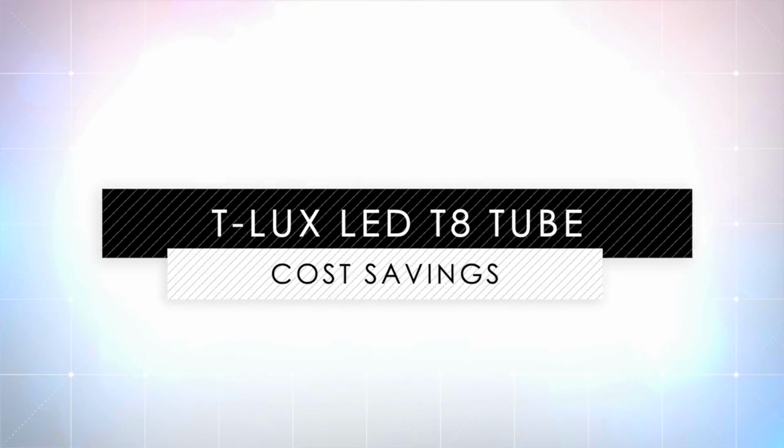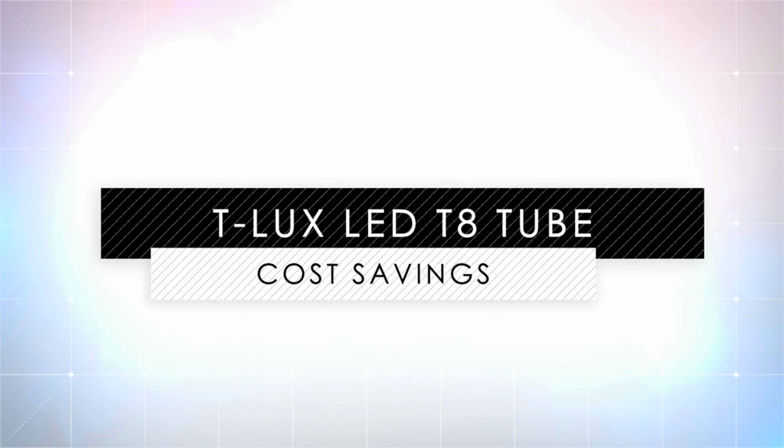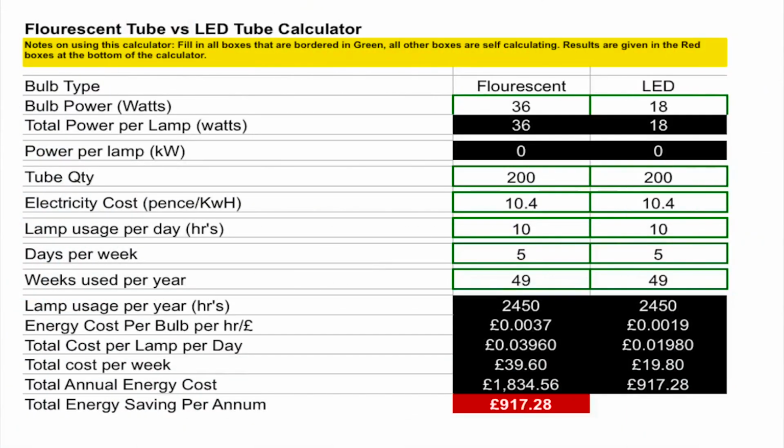To help you further understand the potential cost savings from using LED tubes, let's take a look at a couple of examples. We will imagine an office building with 50 4-foot fluorescent tube fittings that each contain 4 36-watt tubes that are used for 10 hours per day, 5 days per week, and for 49 weeks per year. You can see from the table that using our T-Lux T8 series tubes instead of fluorescent tubes will result in a saving of around 50%.